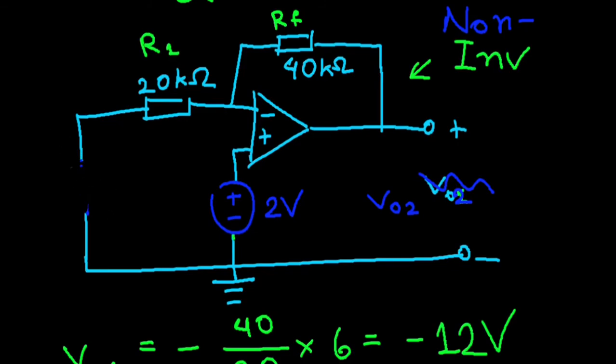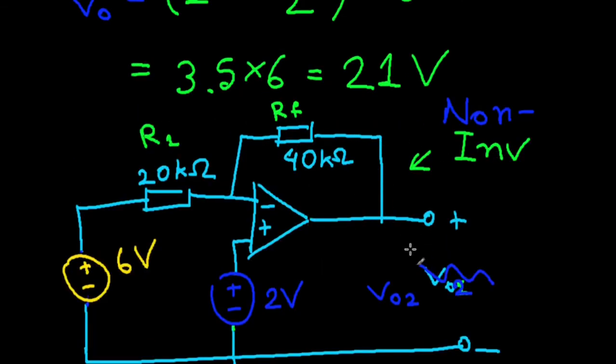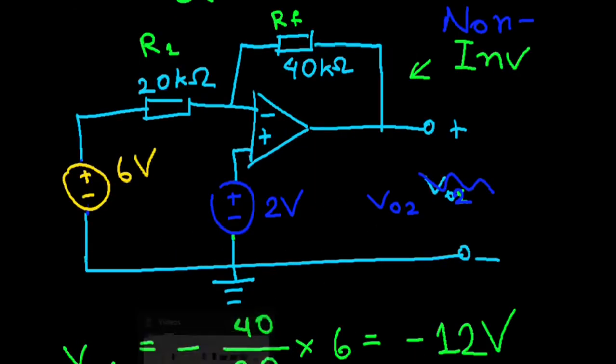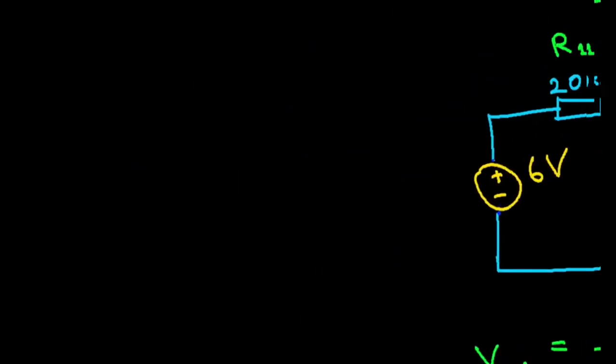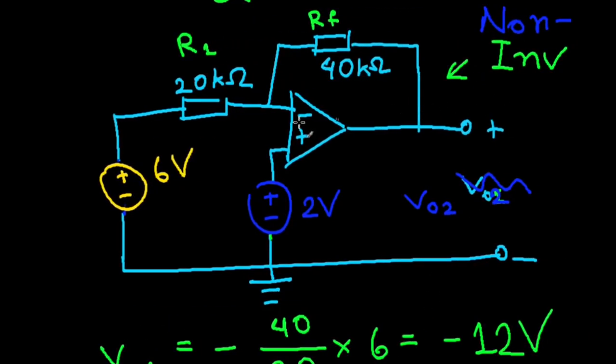But this problem is actually easier if you just treat all of it at once, just as an ideal op amp. I'll actually do that because we got a bit less practice with just ideal op amps. So this is 2 volts. This also has to be 2 volts, right? The input voltages are the same.